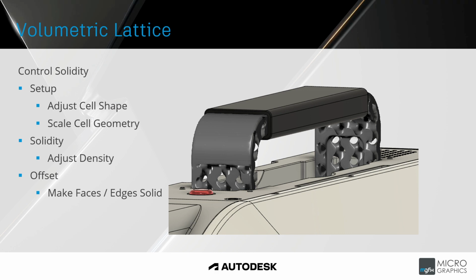And moving from mesh to the volumetric lattice tool, I think the easiest way to explain this lattice tool and what it does is to draw comparisons with what is called infill in 3D printing. I know at least Cura calls it infill, where the material is removed from the inside volume of your part. Now, this not only reduces the amount of material required to print, but also reduces the weight of the part. Using the volumetric lattice tool allows designers to include this internal structure at the design phase, whether it is for function or aesthetics. In the image here, we see the handle of the camera has had material removed to create this open cell webbing or foam-like structure.